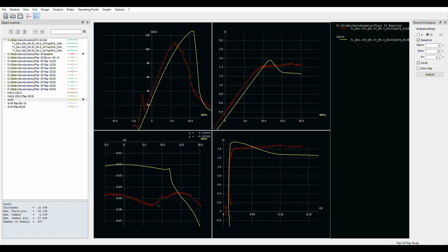Let's look at 10 degrees over here, and we see that we have an inflection here. The pitching moment is changing. It's heading back up. It's got a little burble in it here. I don't know if that's real or not. And then it goes the other direction. So this can be maddening to a pilot trying to fly an aircraft through this. He might feel it, he might not, but if he's got a good stick hand, he might say, something's going weird with the pitch here. So there we go, a good airfoil and a mediocre airfoil.